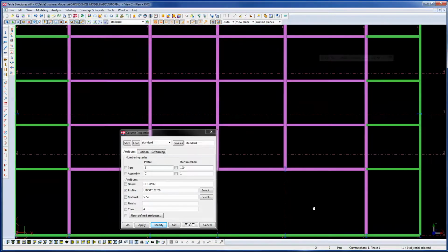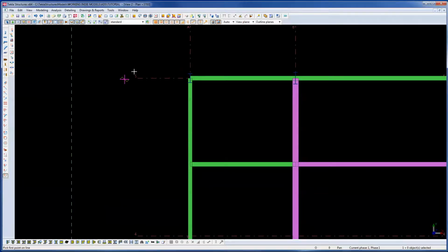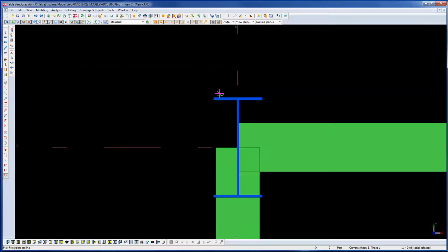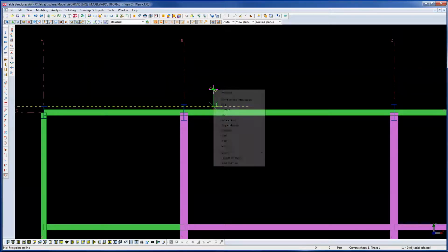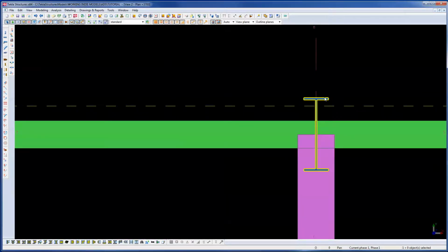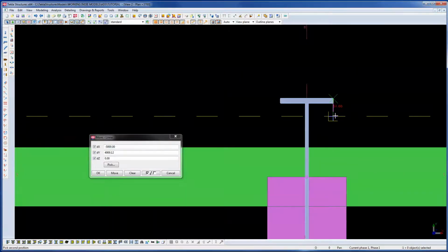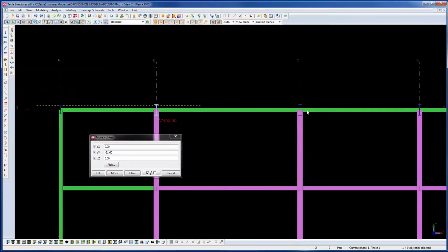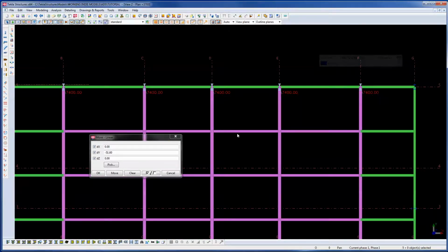Just bring up that plan view. Maintain the sheet in line. Just drop a construction line across there. I can pick anywhere because I've got my ortho snap on. As you can see, that green box also gives you a 45-degree indicator. Actually, 90-degree indicator. I only need to know what one of them is. They're the same section size. Move special, linear. Select them all. And move.